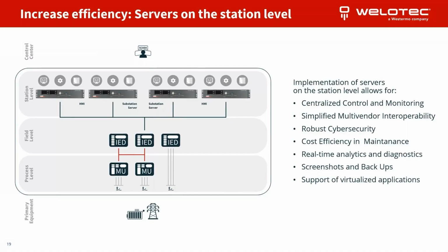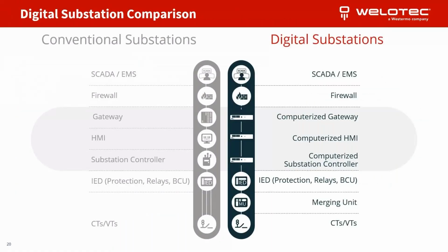So next, we'll talk about the evolution we're seeing today. Ryan mentioned the type 1 hypervisors, and that's what we see mostly today, what we're calling the conversion from conventional to digital substation. Not to be confused with digital twin, but actually digitizing the substation functions on standard compute hardware.